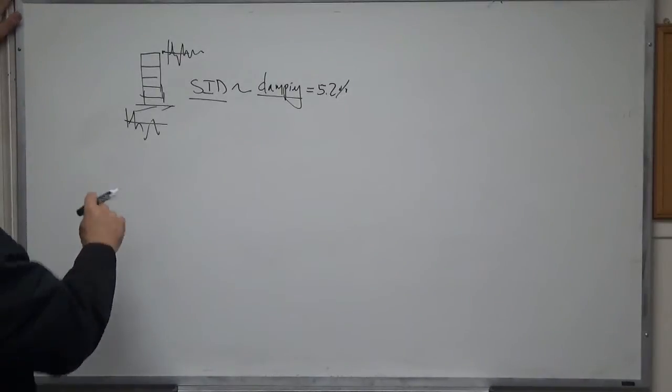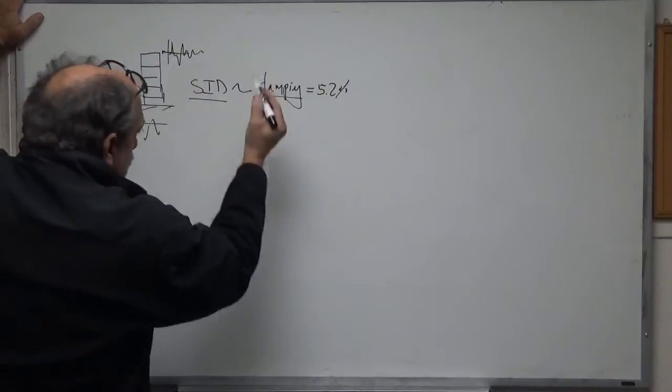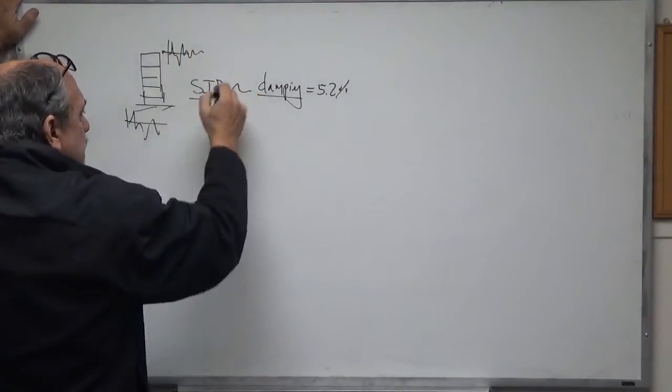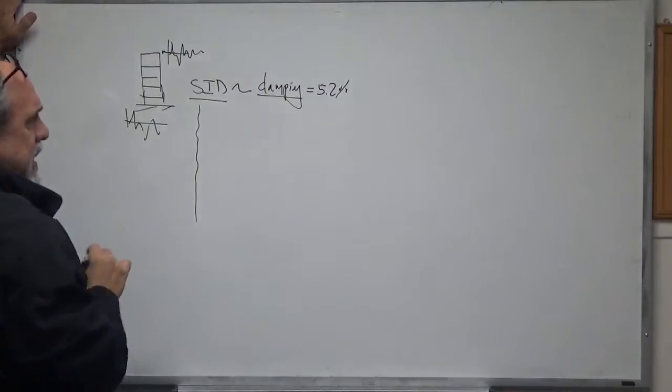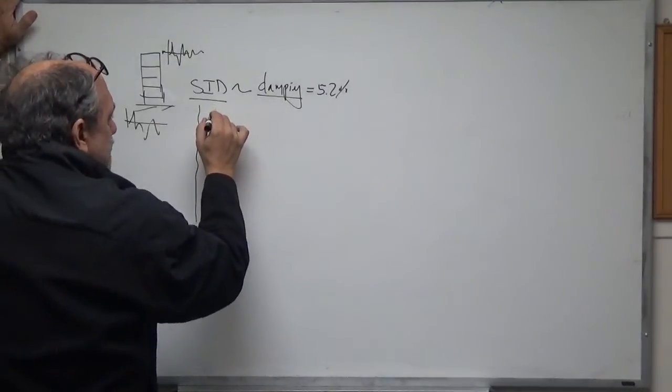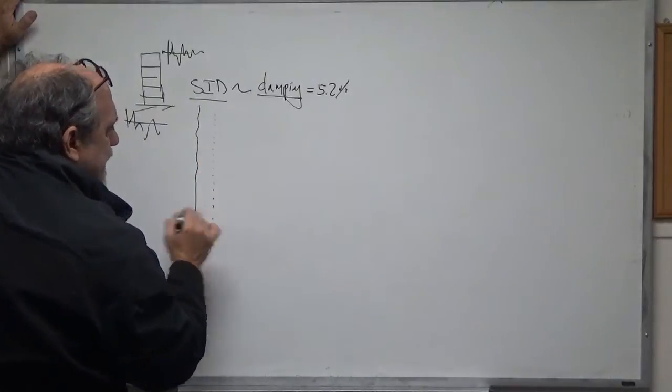And it turns out that we have been measuring the response of buildings for many years now, more than 50 years. And we have lots of data. So part of what we're reporting is we can do system identification with this very large data set and obtain all these dampings of real buildings that were obtained from the analysis, right?